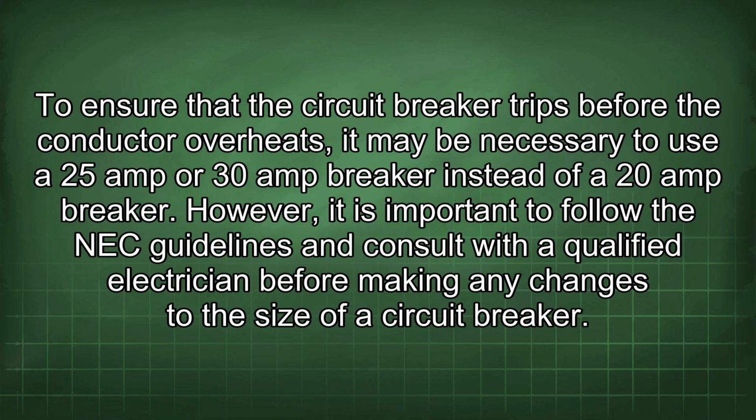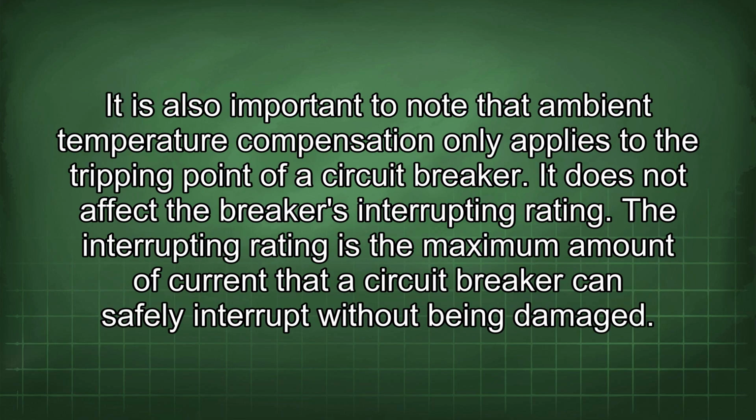However, it is important to follow the NEC guidelines and consult with a qualified electrician before making any changes to the size of a circuit breaker. It is also important to note that ambient temperature compensation only applies to the tripping point of a circuit breaker. It does not affect the breaker's interrupting rating.